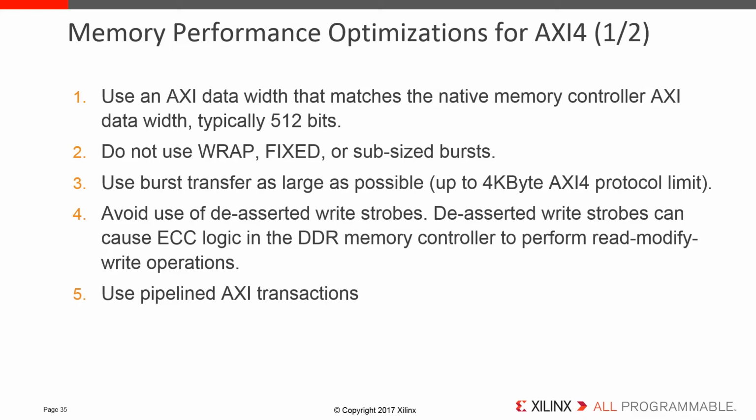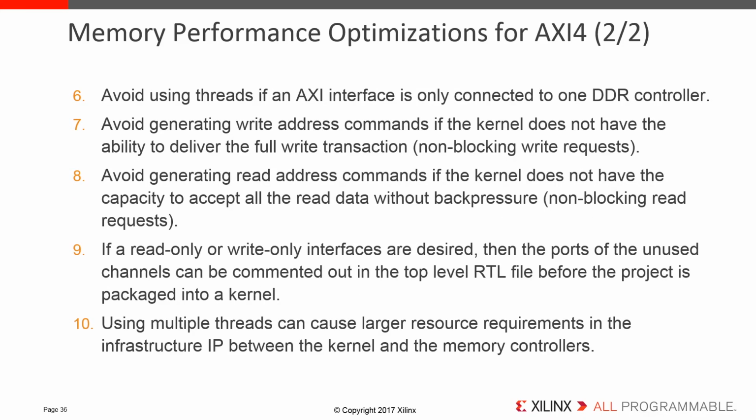Avoid using deasserted write strobes. And take advantage of the split transaction bus architecture of the AXI protocol by pipelining your AXI transactions. Also, avoid using threads or AXI IDs that can consume additional resources unless it's absolutely needed.